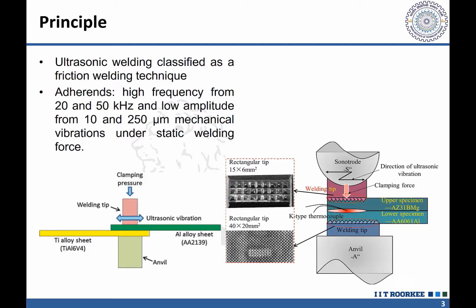So a lot of interfacial frictional heating happens here, that leads to different kinds of effects, which may be in the form of melting or just thermal softening of the metal at the interface.